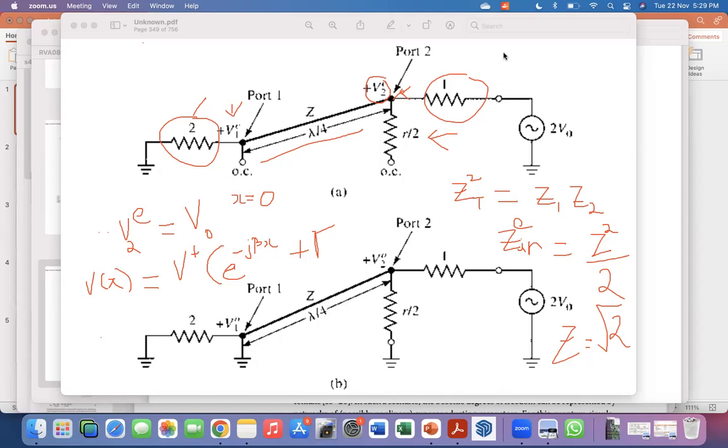Then I do the same thing for the bottom circuit, the odd mode excitation. Then I compute the whole thing. And what I get is that if I put some signal on port 2, how much signal comes at port 1 with port 3 matched, right? That is basically the definition of S12. But S12 has to be equal to S21 because this is a passive reciprocal circuit. So you compute it in the reverse direction because it's easier to split it this way. And then you use reciprocity to say that, okay, the S matrix is going to be like that.